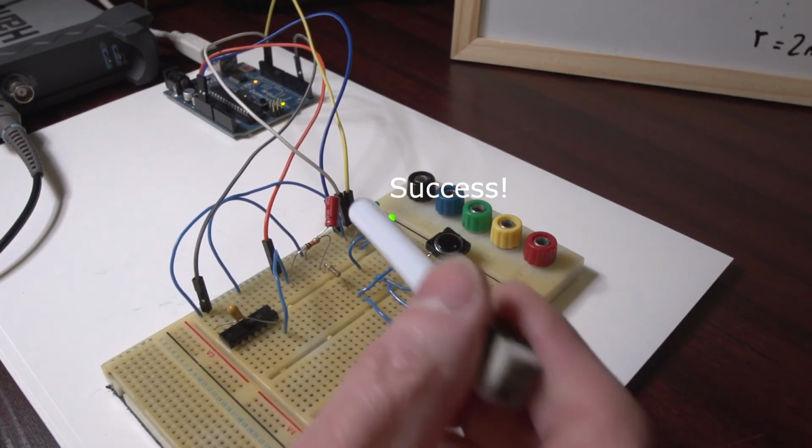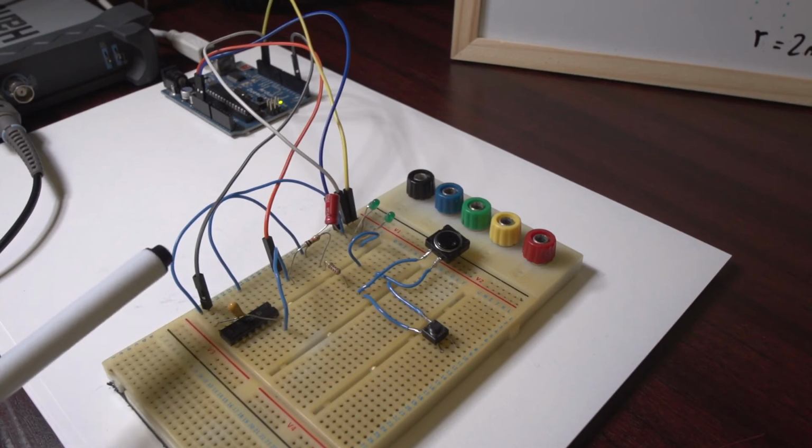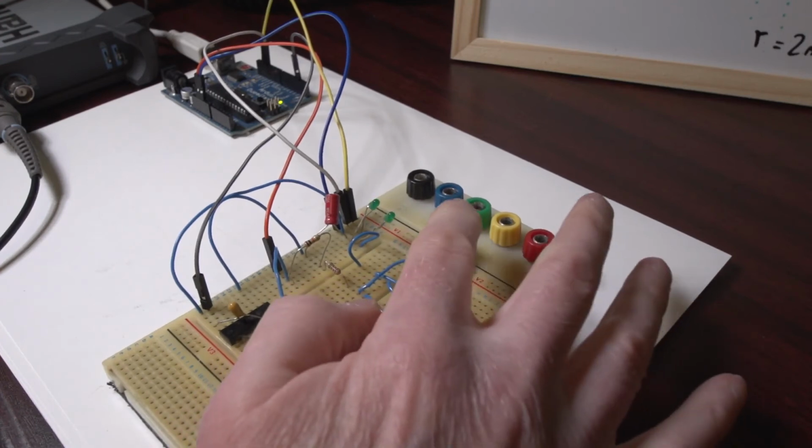We've got the button, we've got the RC time constant here, we've got the Schmitt trigger giving us a really fast rise time output through this grey lead here, and that's going to the interrupt pin on the Arduino, and it seems to be working really well.